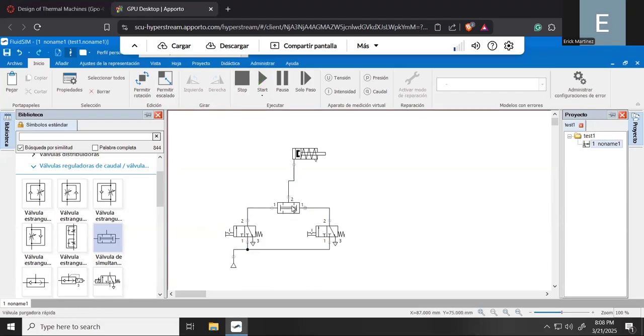And there is another valve that we can use by using the same configuration that is called the shuttle valve. Okay, this shuttle valve has this following symbol, but this shuttle valve behaves very similar to an OR logic function. So you can connect this element to this port, okay, and also you connect this port to this section and this port to this section.